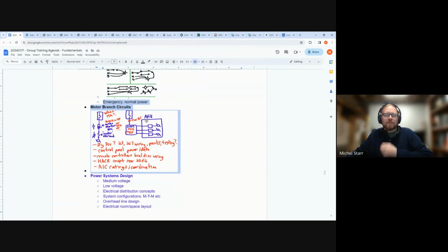What happens if there's something, wires that touch ground or themselves or otherwise a fault, a reason to have overcurrent protection work. The equipment, you don't want it to explode before the overcurrent protection can work. So there's AIC ratings on all the equipment, and that's especially one that we're probably more guilty than others of not really coordinating that well. The idea of putting fuses in front of them used to be okay, or they call it the up and over method, but it can be a questionable practice.